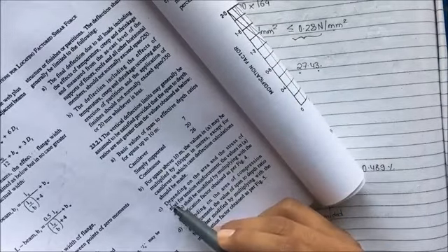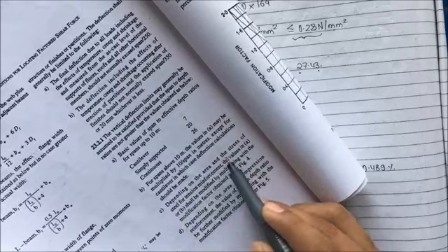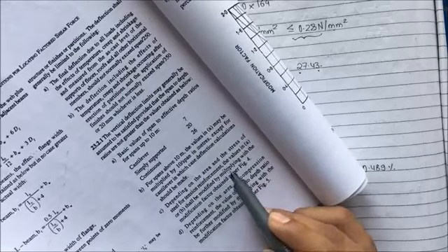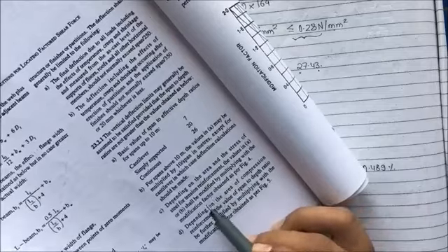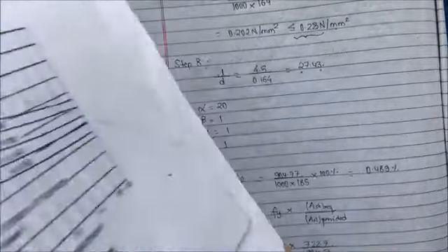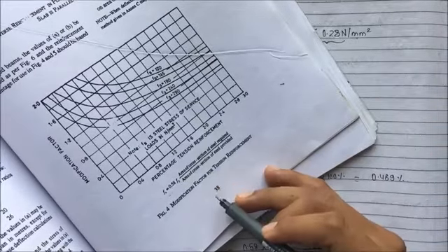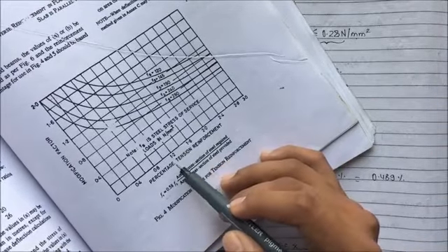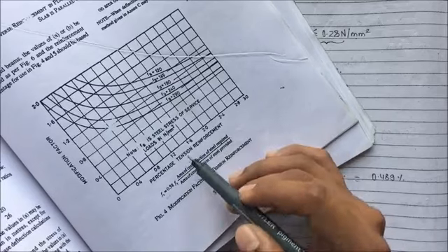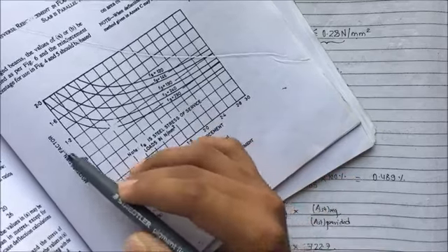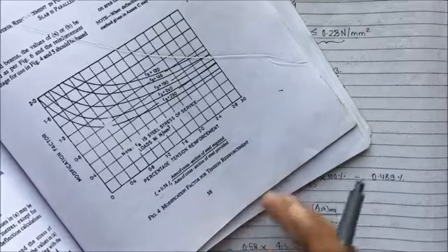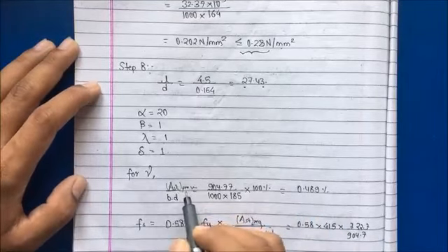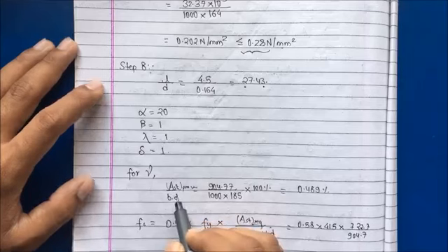let us read out this point C. Depending on the area and stress of steel for tension reinforcement, the value of A or B shall be modified by multiplying with the modification factor as obtained from figure 4. This is figure 4 at page number 38. As it says, for the percentage tension reinforcement we have to take the modification factor, and before that we have to find the value of Fs. For gamma, we have to find the percentage tension reinforcement.